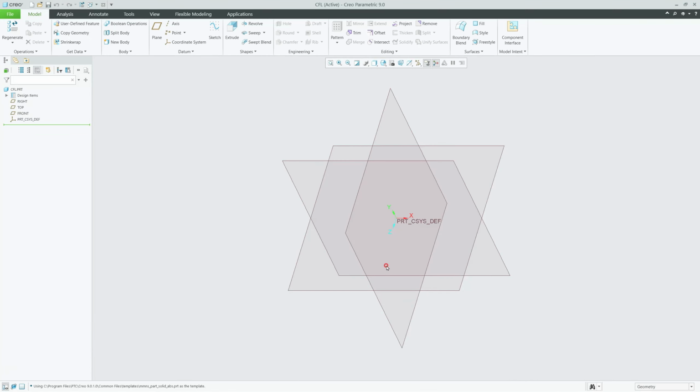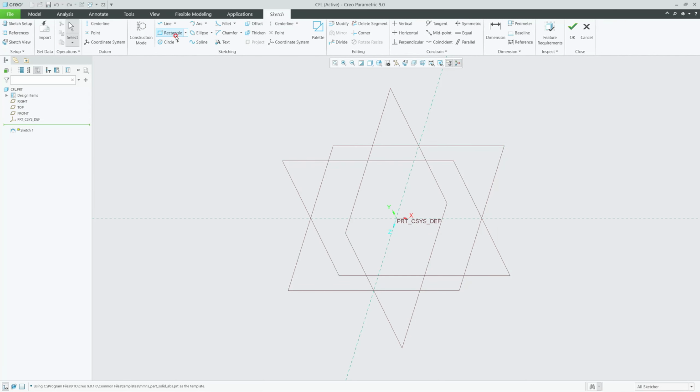Okay, but still the part cannot do our job, because the fuel cell model is just 10 micron thick. So if it's 10 micron thick, we will not be able to plot it. So if you try to directly draw it, we take our top plane and use the sketch and make a rectangle.